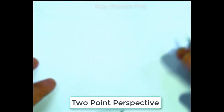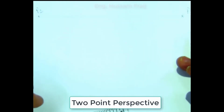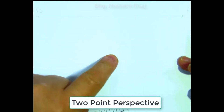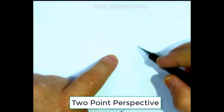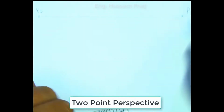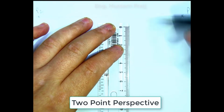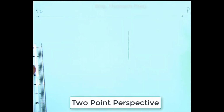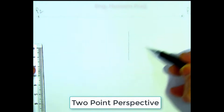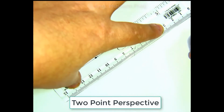Okay, then at a certain point here we have to decide where to put the vertical line, our first vertical line. This vertical line will decide how your cube will look. I will show you an example. If I decide to draw the vertical line here, that means the depth of the part is less than the width. See?